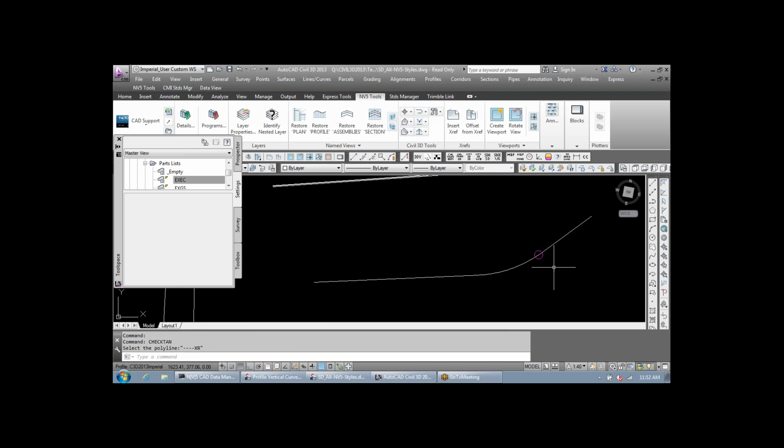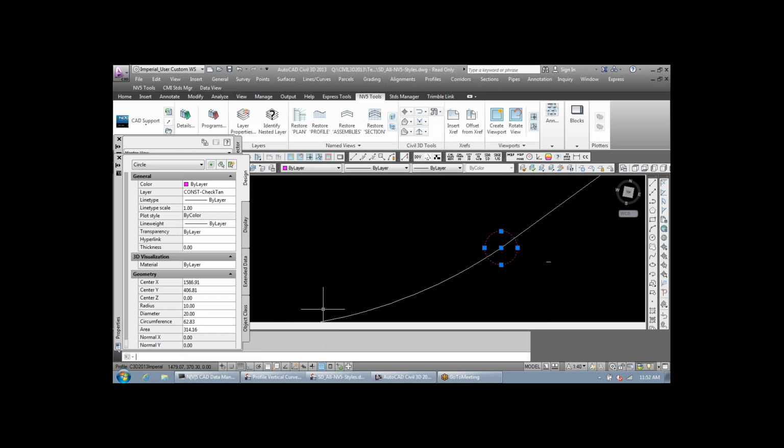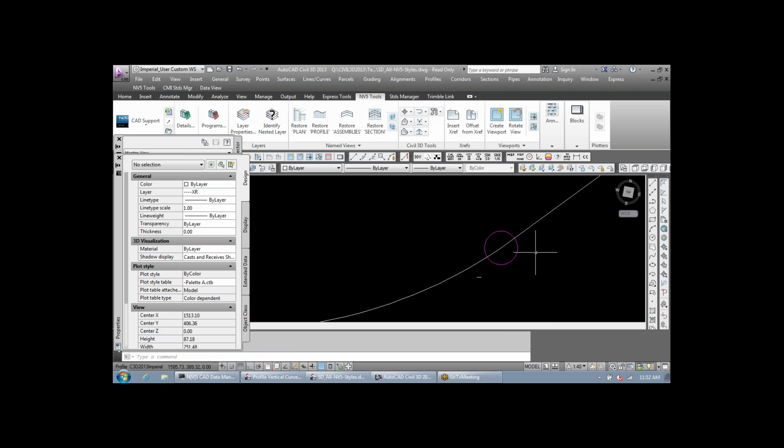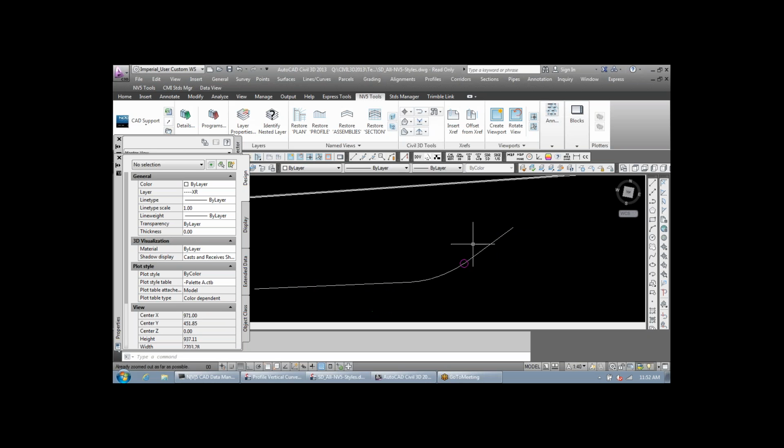It will save you a little bit of a step. Right now I think this guy's set to either a 5-foot or 10-foot radius, 10-foot radius. Let me know how that works out for you guys. Depending on how long your alignment is, you may want that to be bigger. You may want it to be smaller. I don't know. I just threw 10 in because it seemed like a good radius of the circle.